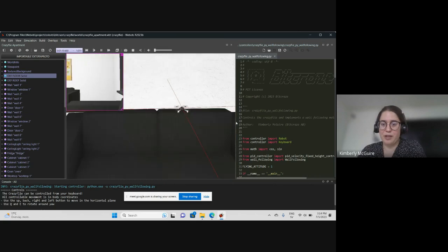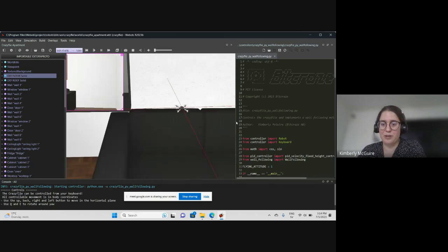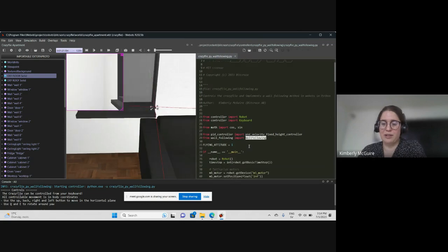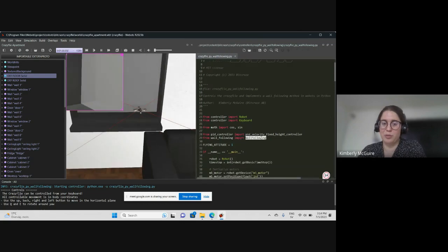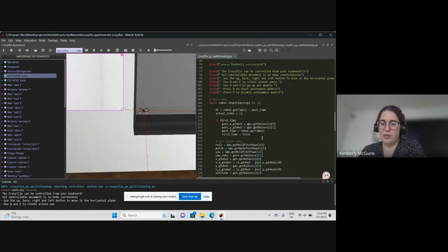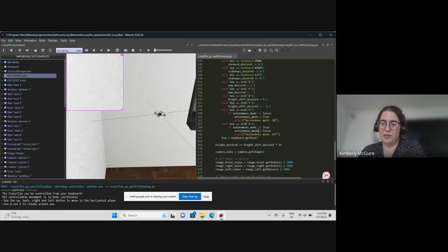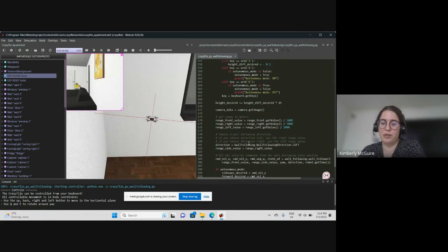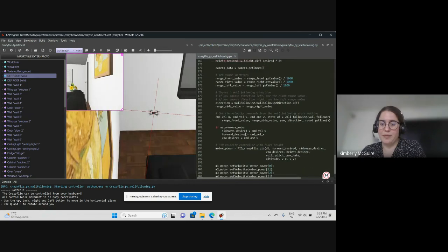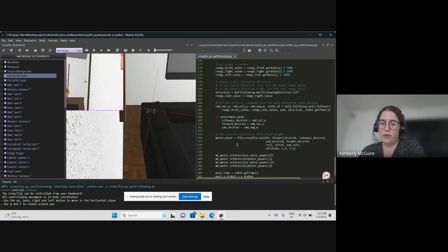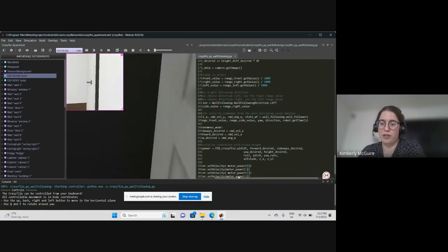So while it's flying, we can take a quick look also at the control right here. I've added some extra code here that's doing the wall following, that has the wall following state machine. If autonomous mode is enabled, it replaces all the sideways desired and forward desired or yaw desired with the one that comes from the wall following state machine.